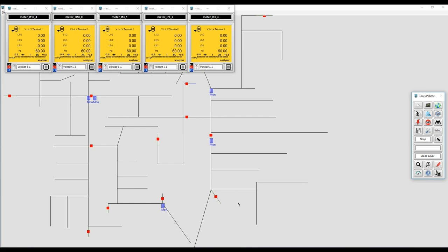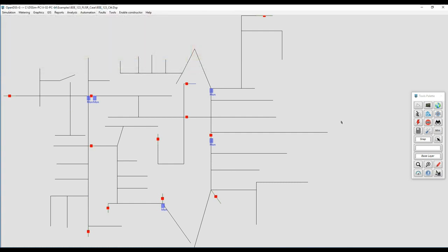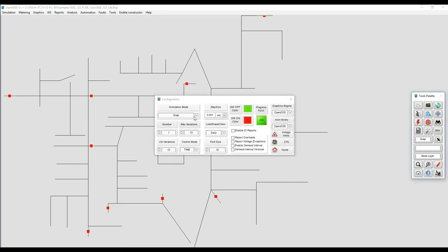What we have in this feeder are 5 zones, which are described by the switches and the location of the reclosers that we have. We have placed a monitor to check each one of the zones separately. In this feeder we have one substation, we have 3 tie points to other feeders to restore the service in different zones, and we have 3 PV systems.